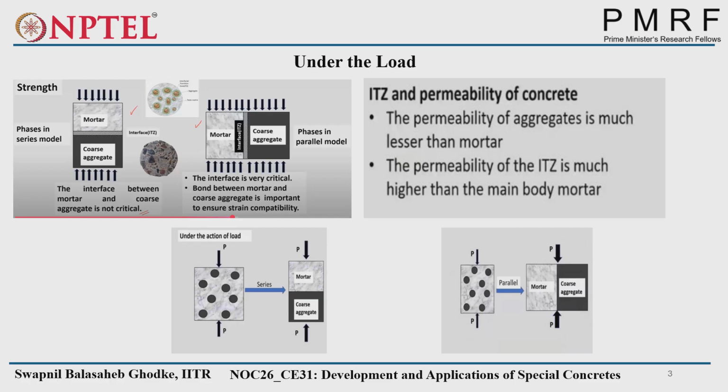So ITZ and permeability of concrete have a direct relation, because of the higher amount of water in the interfacial transition zone. Some amount of water will evaporate and will create voids or pores.